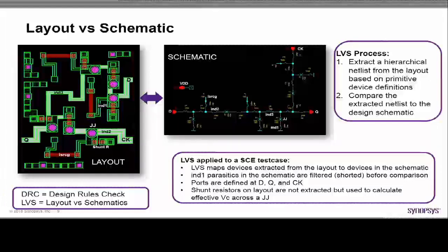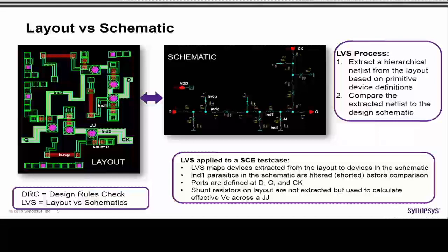It's not enough to be able to do each one of these tasks individually. That's not that hard. The trick is to be able to invoke from within the same tool all those tools that will do DRC, LVS. For example, you want to take a window, DRC it, find out the errors in a small chunk, fix it, do the LVS, or invoke simulation, see if what you have captured so far meets the bill, and so on.